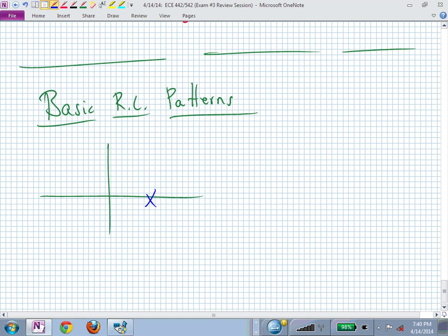This root locus is right there. What's the red line give you? What's the root locus telling you? All the possible closed-loop pole locations as you crank up the gain K in a closed-loop configuration where your original system had a pole at wherever this was located.